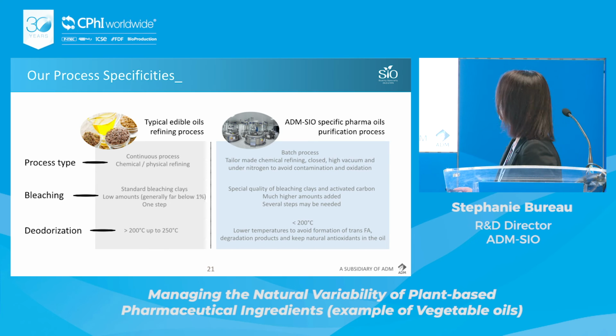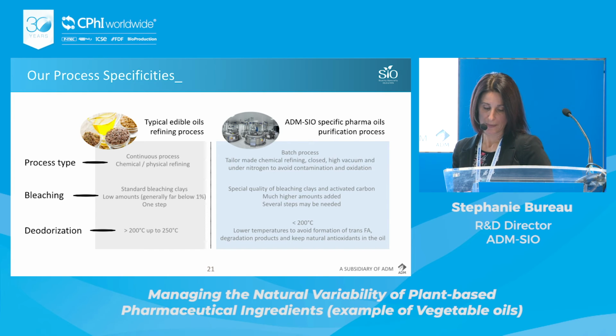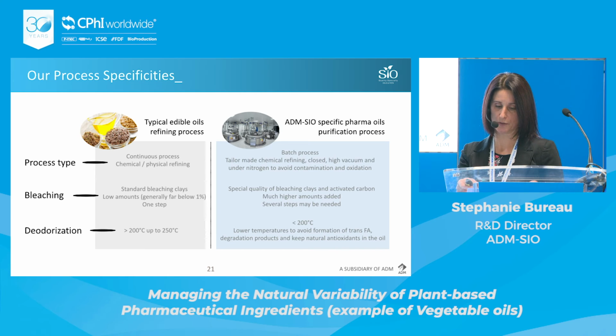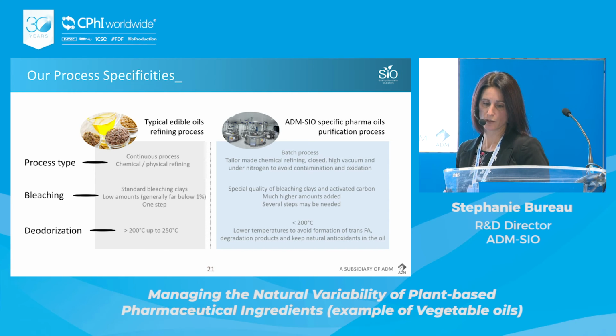The last step of the purification process is the deodorization. It allows us to remove remaining free fatty acids and oxidation compounds that are responsible for taste and odor and can be damaging for the good conservation and stability of the product. This step allows us to reach very low levels of acid and peroxide values, so as to guarantee the good stability of the final product.